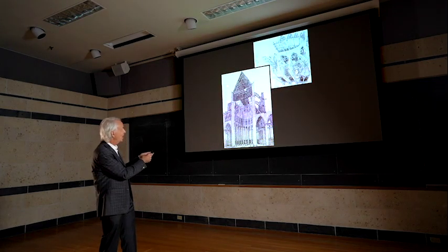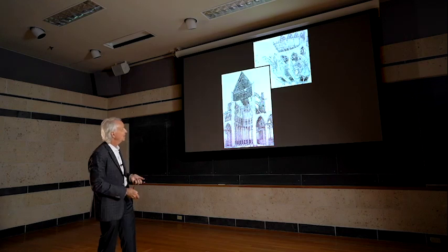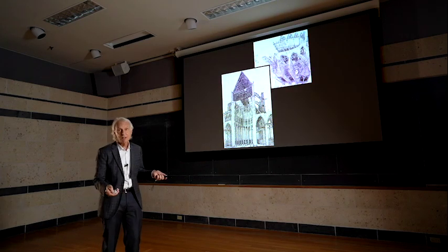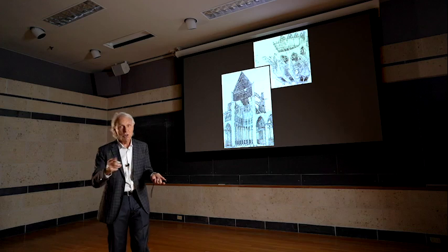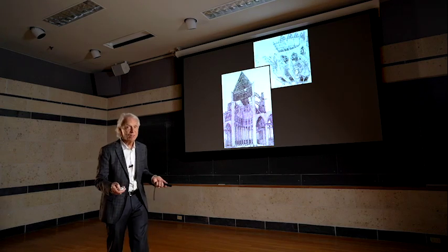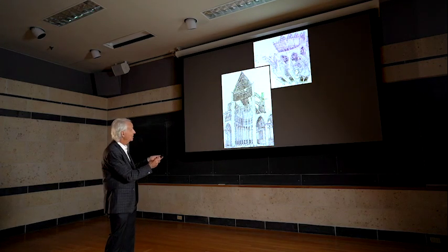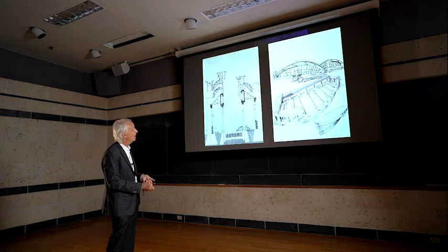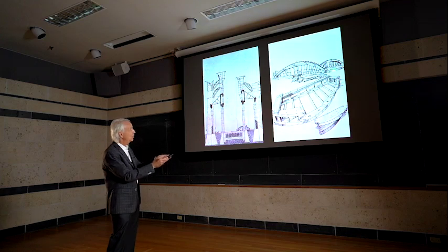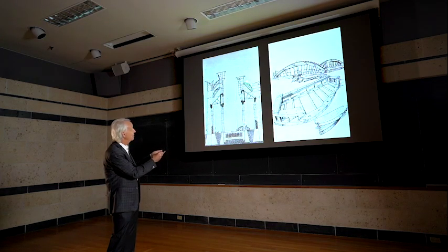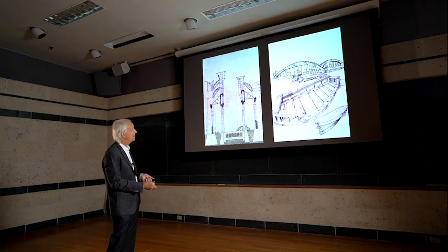So finally, they've got all that up there. They're having to build these flying buttresses that go out from the side there, as we have talked about before. An arch is a fantastic structural shape when it's complete, but until it's complete, it's worthless. So you have to build centering like this out of wood, and then you're taking those wood pieces, putting them up here, and then building the masonry on top of that piece.